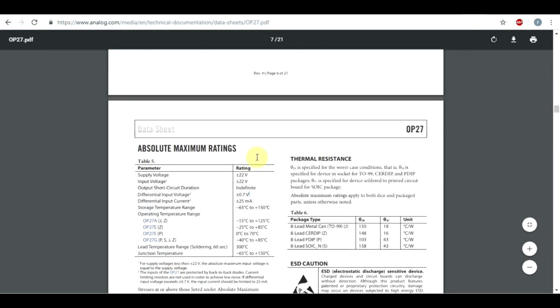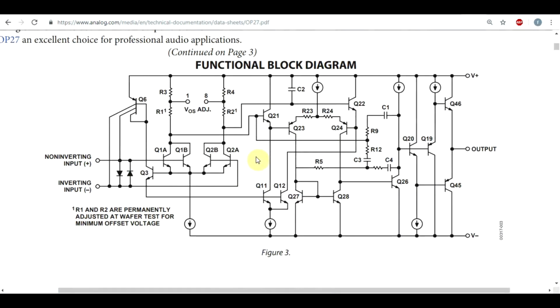So what's going on? Well, if we have a closer look at the input stage, we will see that we have these protection diodes between the two inputs. And if you drive the difference between the two inputs to more than 0.7 volts, then you will destroy these diodes, leading to the destruction of the op-amp. Now, why would you bother putting these diodes in? I mean, aren't they just a bother? Well, these things have a very good purpose.